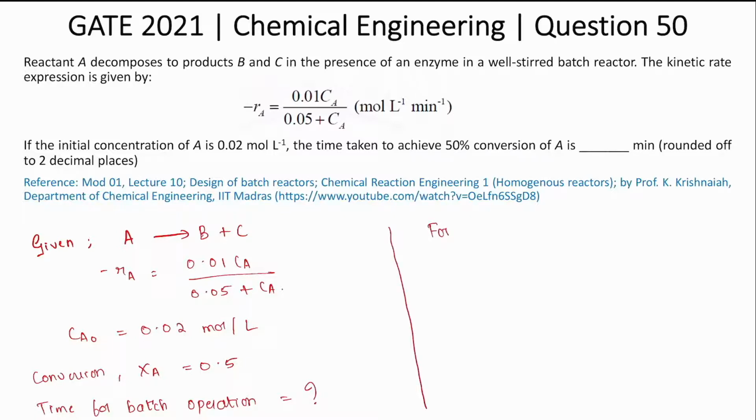So by using the energy balances or material balances, we can derive the equation for batch reactor as t batch is equal to Ca0 into integral of 0 to Xa dXa by minus Ra.